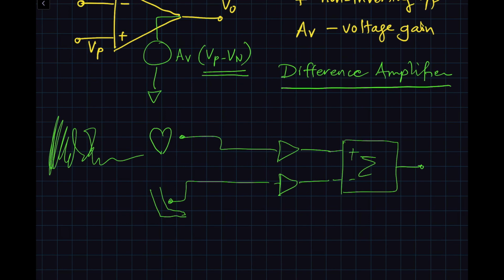And here is something like 50 to 100 millivolts of 50 hertz hum, we call it, that's riding on each side. So let's say there is a 50 hertz tone here, and there is a 50 hertz tone over here. These are large and noisy signals which are on each lead. Now, if we amplify them separately, our desired signal is a small signal that's riding on top of this signal.